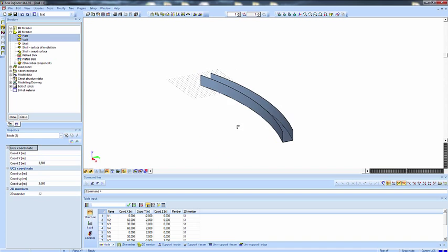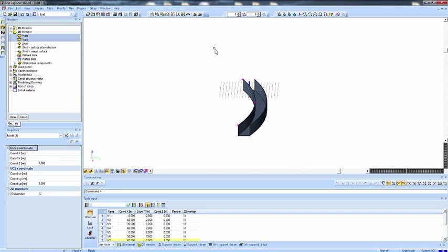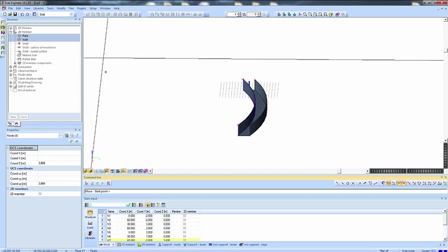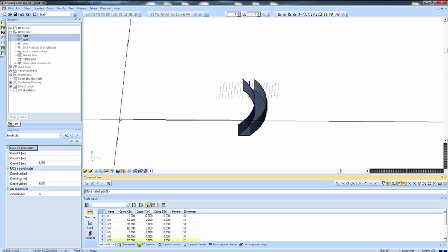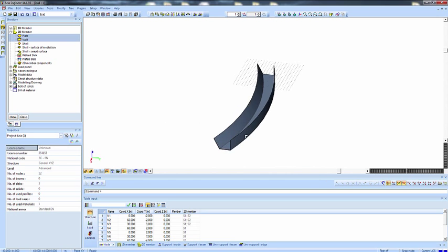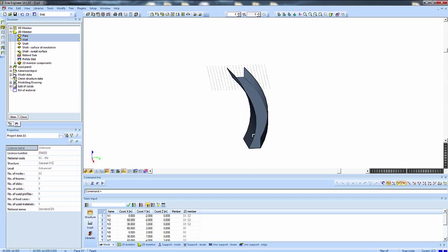Now, as I've indicated, Scia Engineer is very flexible, which means, for example, this wall is defined by 6 points. As you can see, it is defined by the points for the upper and the lower edge. I can choose those points at the upper edge, and I can just move them. Let's say I'm going to say modify move, and I'm going to place them according to the vector from origin to 0, -2. That means I'm going to place it 2 meters further in the y direction. You can see that it easily becomes a curved element.